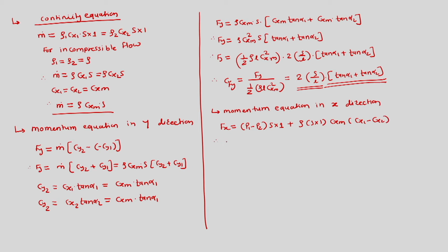So we have, for incompressible flow, we can write P1 is equal to P01 minus half rho into C1 square. Basically this expression says that P01 is equal to P1 plus half rho V square. This is strictly for incompressible flows where total pressure is equal to static plus dynamic pressures.